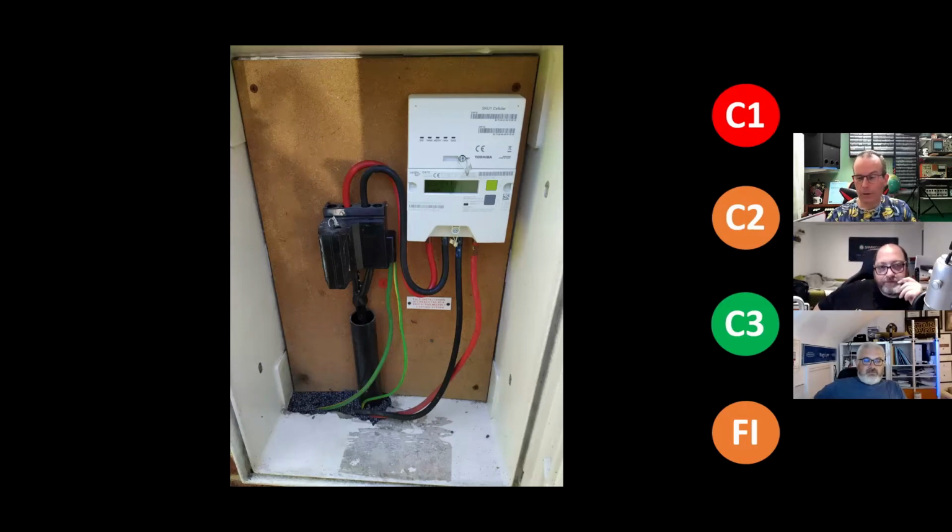Are they single insulated cables, John? No, they are the insulated and sheathed type. Okay. But yeah, they're 16, which is obviously a bit on the small side. But it's an interesting earthing configuration, because the side of the cutout you can see is insulated. Where we had a block exposed, they've obviously changed it over time, and that's insulated. But you've got two earthing connections. There's two conductors there.